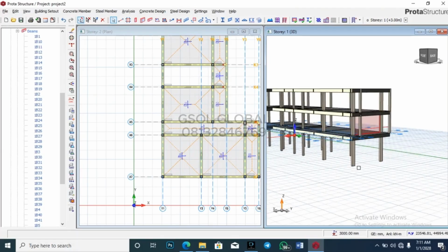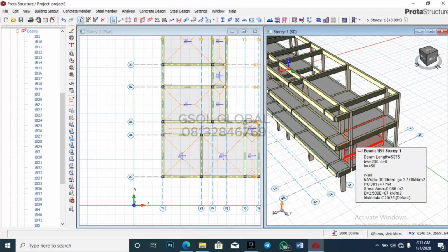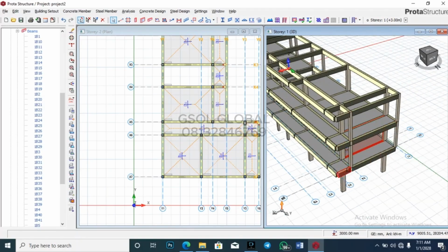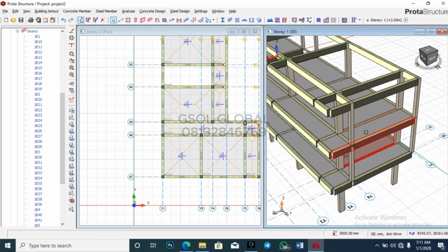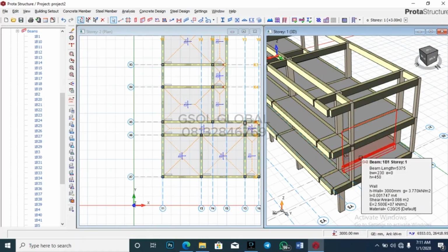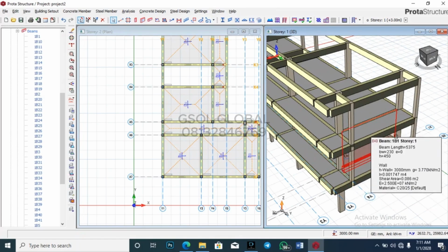It's now good. There is something we did when we were trying to use the cantilever method for this, but we did that check and saw that the cantilever method will not work for this particular structure. So we have to brace it more with columns and beams. Look at this cantilever beam down here, we have to brace it more. That erased the cantilever slab all around the building. So we don't have cantilever slab again, and we don't need our parapet load any longer. It actually edited that in our drawing, as you can see.